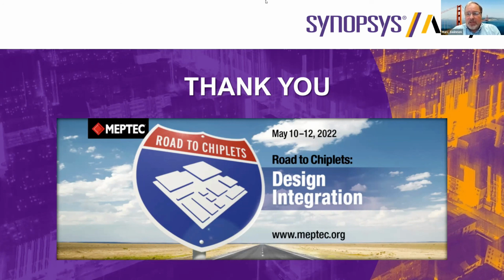Some of them are simply additive, like resistance extraction, RC extraction. There you can extract each chip individually and the TSV or the bump going between them and just add them together. Those are simply additive. Some of them can be addressed through reduced order models. For example, the chip power model. So the power output of a chip depends on its temperature, but the temperature depends on its power output. So you've got a bit of a chicken and egg there.